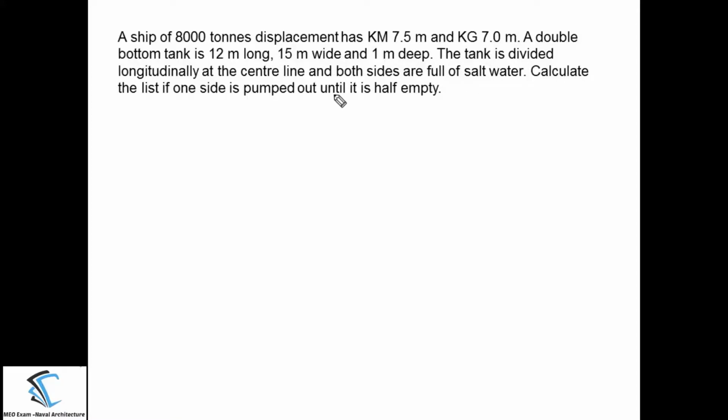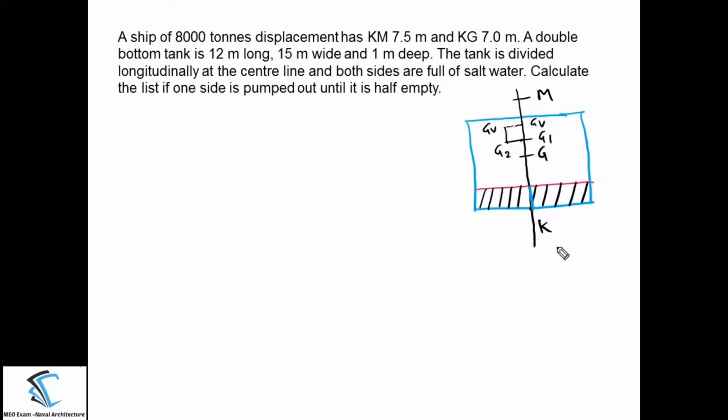The tank is divided longitudinally at the center line. It means that there is a center girder and both the sides are full of salt water. Calculate the list if one side is pumped out until it is half empty. Let's start the solution of this numerical.